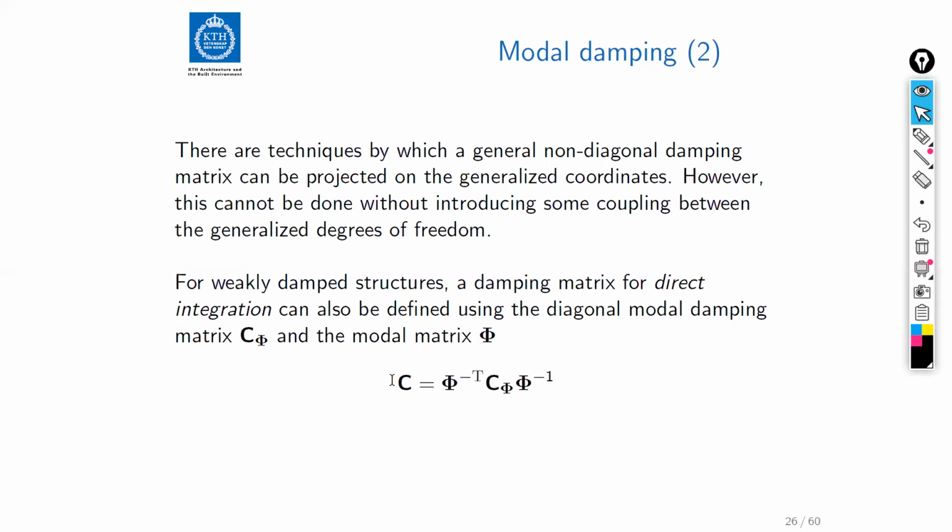So even if we have a million degrees of freedom, the matrix that we use to define the stiffness or the mass will still have 1 million elements on its main diagonal, but the off-diagonal values will be maybe a factor up to 100. So the total number of non-zeros in one of those sparse matrices would be like 1 million times 100. But in this case, you would get 1 million by 1 million if you drag this all the way. So this is not applicable for general systems.